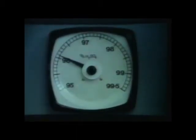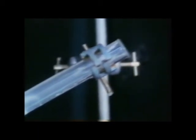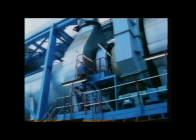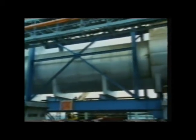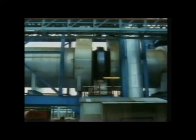There are many uses for sulfuric acid: making titanium dioxide pigment for paints, making fertilizers, making detergents. Here at the Rock Savage plant, much of the acid is used to produce hydrogen fluoride. If you heat calcium fluoride with concentrated sulfuric acid, the gas hydrogen fluoride is given off, which forms the very dangerous and corrosive hydrofluoric acid with any water that's present. It's done on an enormous scale industrially, in huge rotating kilns. Everything inside is completely dry, and under these conditions, the hydrogen fluoride doesn't attack the steel which the plant's made of.